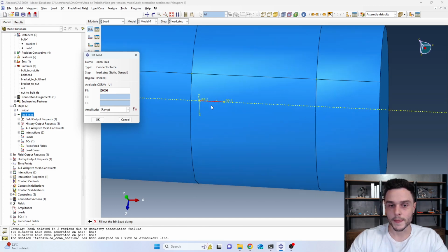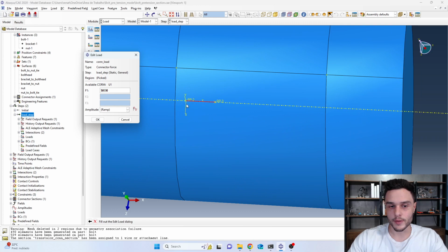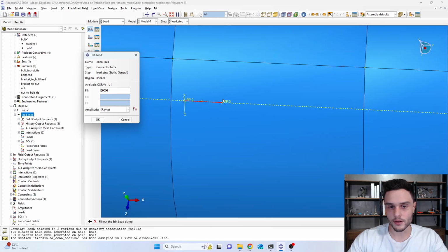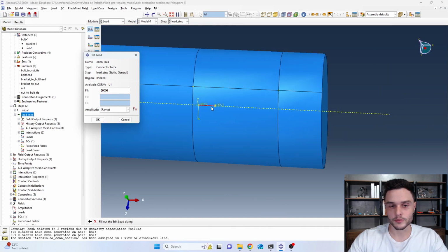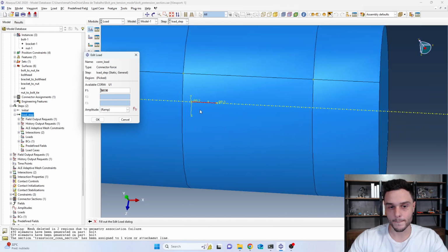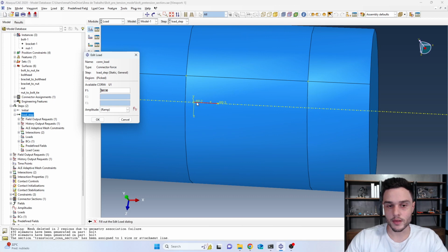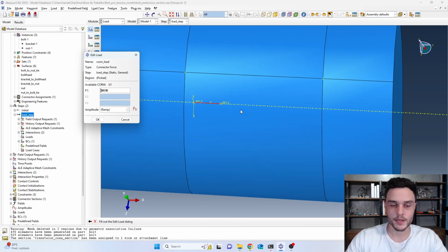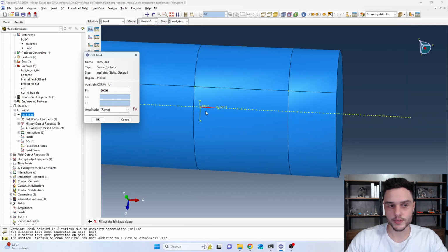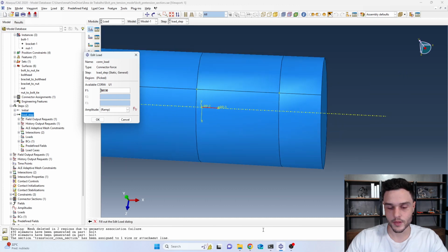traction. Okay, but when we create the connector, automatically the x-axis is from the first to the second node. Then this rule of positive equals traction and negative equals compression is true. Okay, I'm telling you this because many people use ENSA or HyperMesh to model connectors and to actually set up the model. And in there, we should create the coordinate system manually. And if we create this coordinate system with the x-axis to the left, then we should be aware that positive will mean compression.